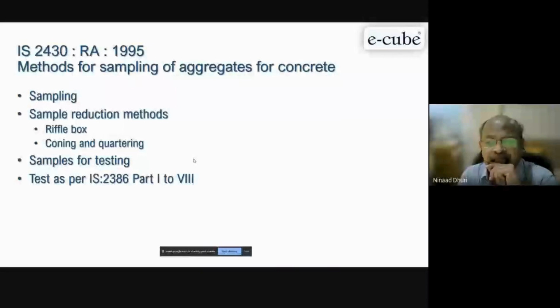When you are producing a large amount of concrete, if your grading is not okay and a representative sample is not there, you may suffer a lot of problems in the fresh properties of concrete. When you talk about particle size distribution, the particles have to be represented. Only then can you blend 10 mm and 20 mm and get the proper grading. Otherwise, you will have issues in concrete production later, and you will not be able to find out what has happened.